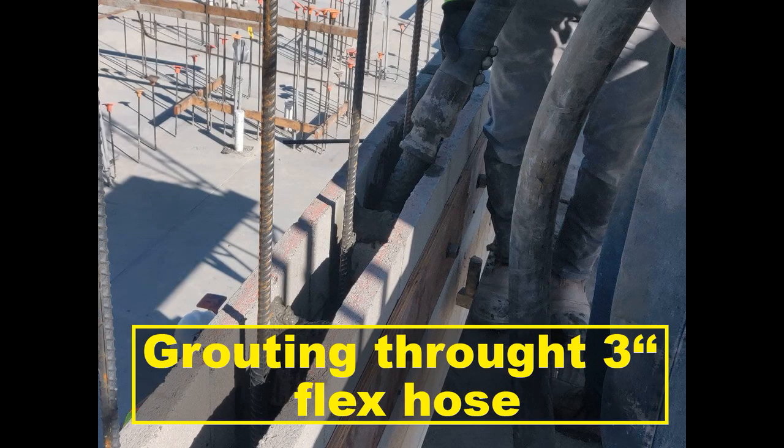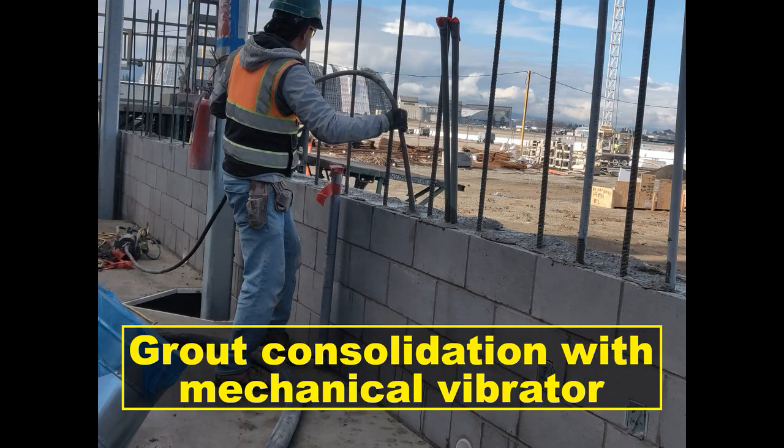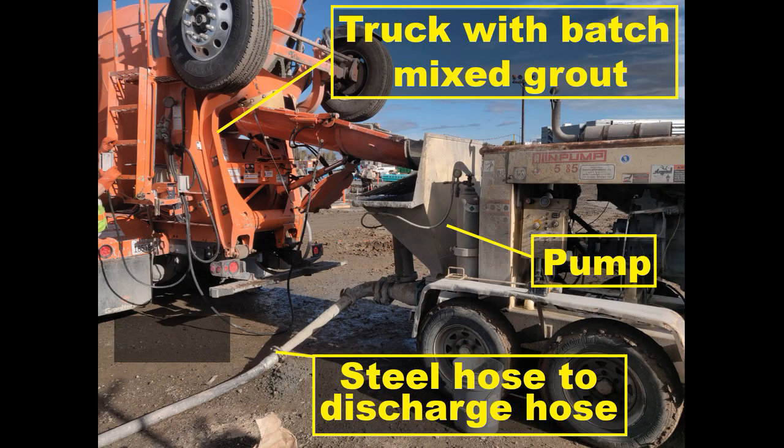Do not change proportions and do not use materials with different physical or chemical characteristics in grout for the work unless additional evidence is furnished that grout meets the specified requirements. Use ready-mixed grout that conforms to ASTM C476.